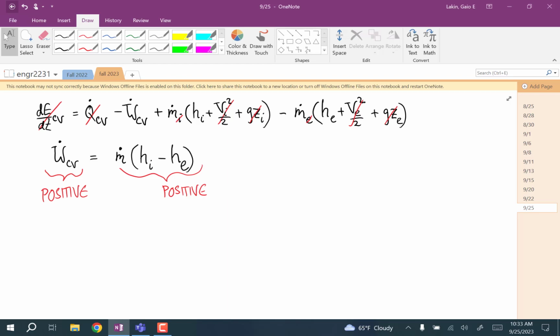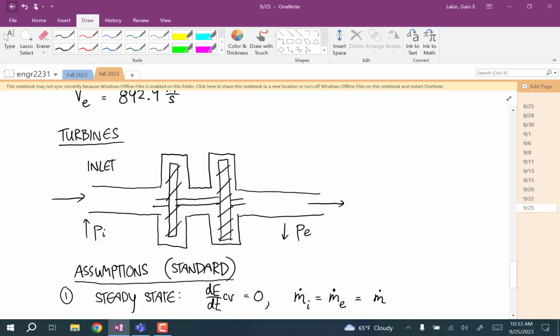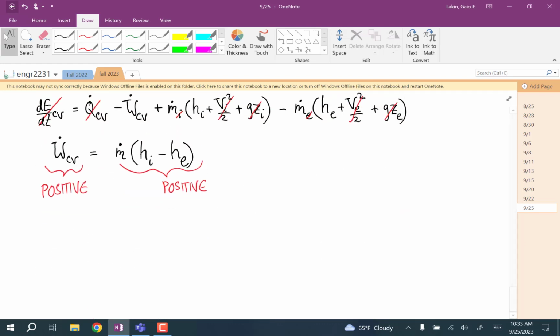Later in the class, when we talk about power plants and power generation cycles more realistically, we'll talk about some of the practical concerns here. As you lose enthalpy, it's very easy to go from a superheated vapor to a saturated state where you start to get condensation, and that condensation is very, very hard on turbine blades.